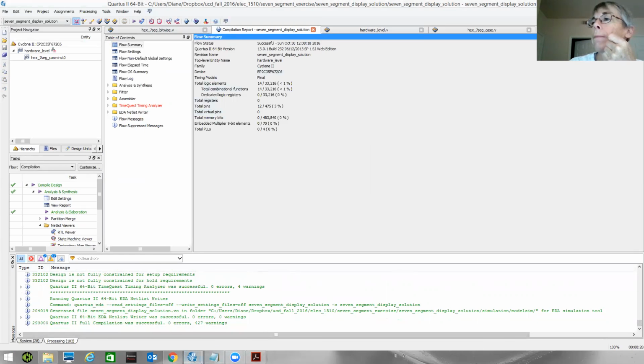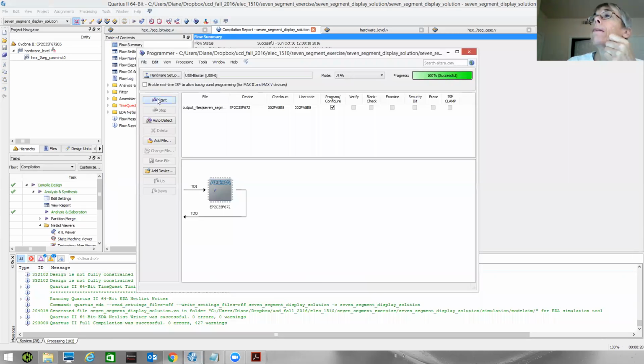Okay, let's program. Notice my hex 0 is turned completely off because my switch 4 is at a 0. If I flip switch 4 on, notice we've got a 0 because 3 down to 0 are zeros. If I then put a pattern of 5, I've got that on here, but now if I turn switch 4 back to 0, it turns my display off. So I can control, with another piece of hardware, whether I want that display to be on or off.